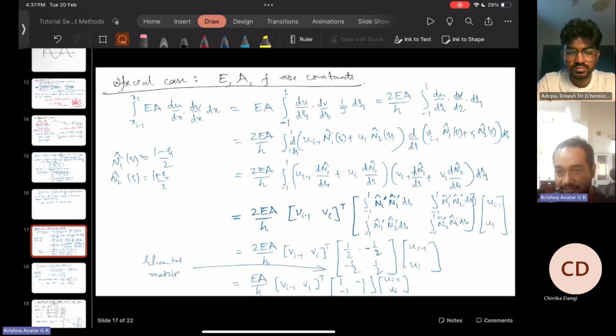All that we need to do is proper bookkeeping. However, if E and F are constants, then it becomes a completely uniform bar. So then it's just having one isoparametric element, defining its integral over a domain, and then assembling it. That is the only job we have to do, so the job is much more simplified.